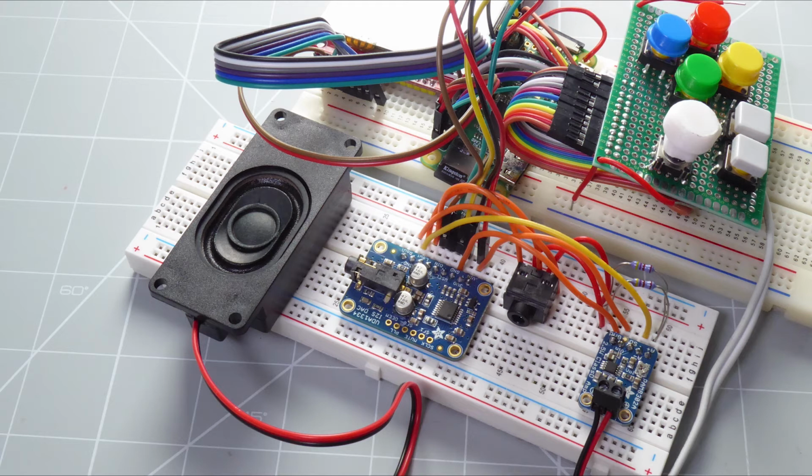So now that we've got some hardware connected up, we do need to get this I2S signal out. By default, the Raspberry Pi doesn't have that I2S signal available on the GPIO pins. So we do need to have some extra software which will help us configure our GPIO pins and then generate this I2S signal, which we can then take and feed into our hardware.